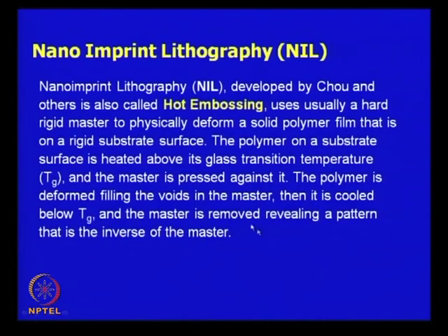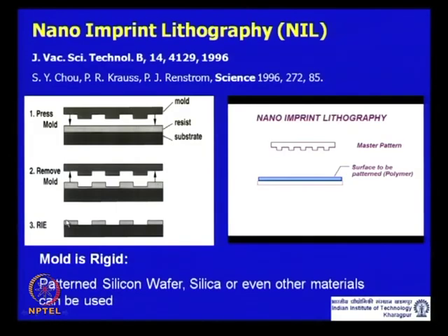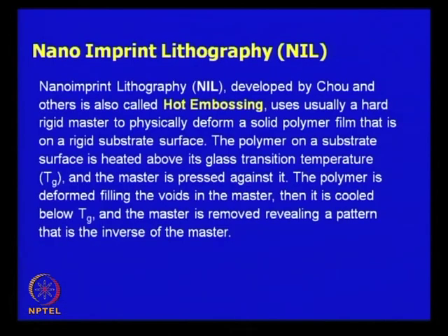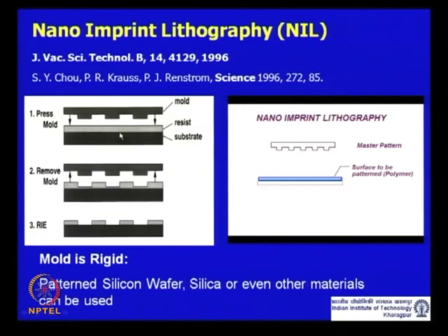You see that in the classical sequence or the definition of nano imprint lithography, there is no mention of reactive ion etching, because nano imprint lithography as a process does not require this RIE. Nano imprint lithography will lead you up to stage 2 on the figure shown on the left hand side. If you require access to the substrate, you additionally would like to apply reactive ion etching. So, in principle it is something very, very simple.